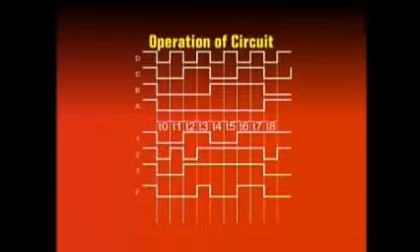The operation of the circuit, which is based on the product of sums simplified expression, also proves that the product of sum based expression determined from the truth table and the Karnaugh map results in a circuit which operates in an identical manner to that of a sum of product based circuit.